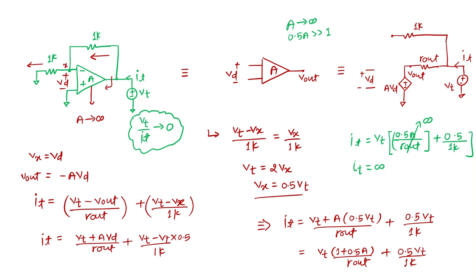Okay, so this is exactly what we are considering here. I'm considering the internal model of the amplifier itself, and then we are calculating. But directly also you can see for any voltage-to-voltage amplifier with this particular feedback topology, we usually see the output impedance reducing when negative feedback is there. If simply I tell you this is a voltage controlled voltage source, with resistors R2 and R1 and this is the input.